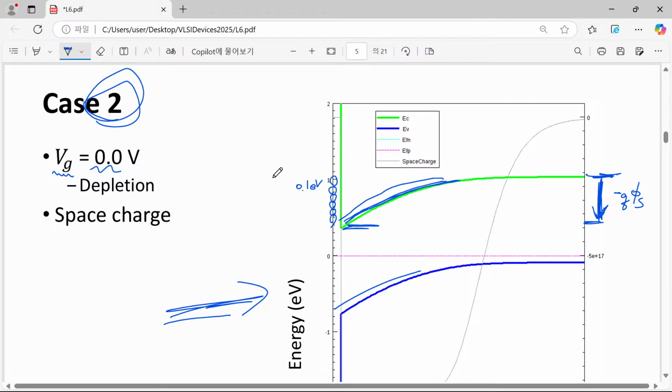That is the key difference, because please note that both electron density and hole density follow this term, n_i exponential phi over thermal voltage, and hole density also follows exponential dependence on our electrostatic potential.